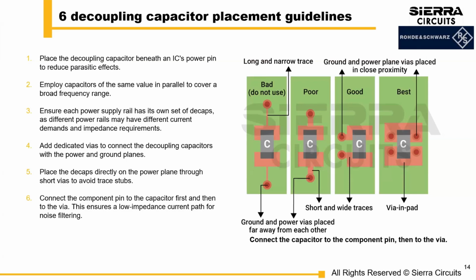You can ensure that each power supply rail has its decaps, as different power rails may have different noise characteristics and current demands, as well as the other items on the slide.